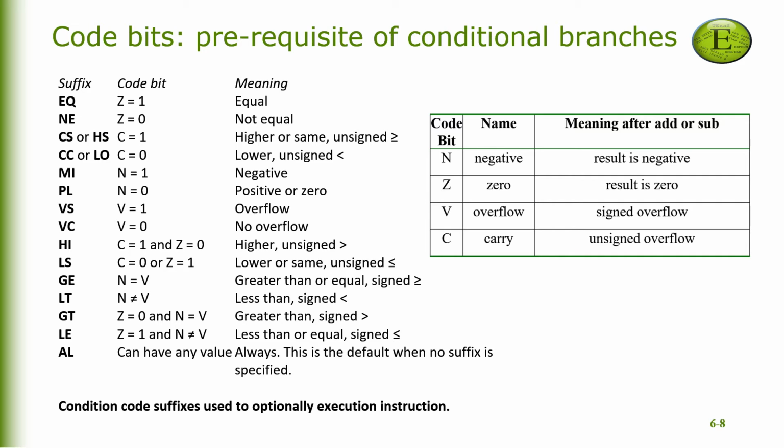To describe that and to understand it in more detail, let us look at some examples. The check of equality. When we wish to perform the equality check, we can just check the status of the 0 flag, because the previous instruction may have compared the 2 numbers, and if those 2 numbers were equal, then that instruction must have set the 0 flag to 1.